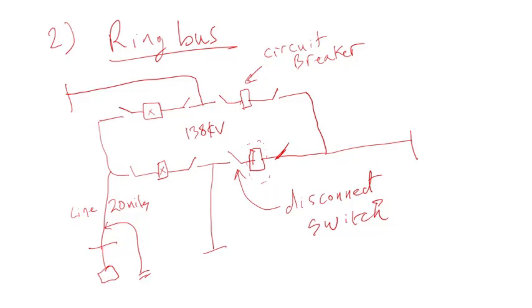If a breaker fails, say with this line to ground fault, these two breakers have to trip to isolate this fault. Let's assume this one here somehow was not working properly. Then it's going to transfer the trip to the next breaker, which is this one here.